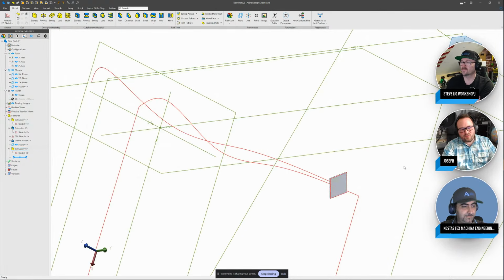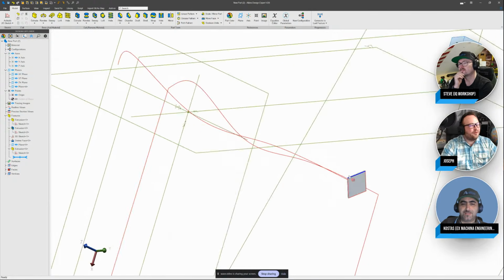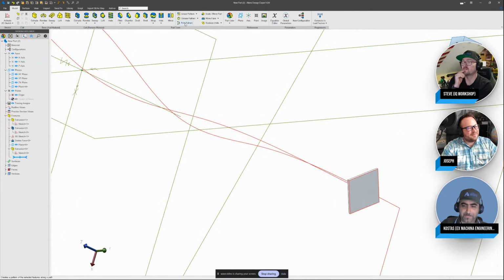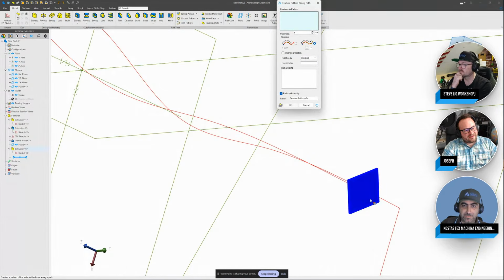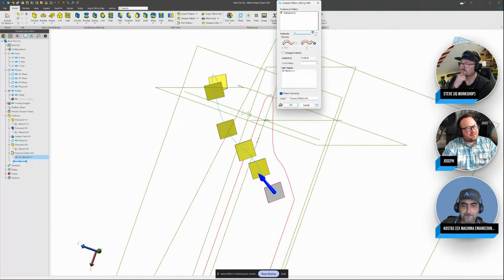So I've got a square. A square has 4 corners. And so I'm going to be planning on making 4 different sweeps. We can do a hexagon if we want 6, an octagon if we want 8, whatever we need. But 4 is plenty for what I'm doing here. I'm going to make a path pattern. We're going to pattern this extrude down this path.